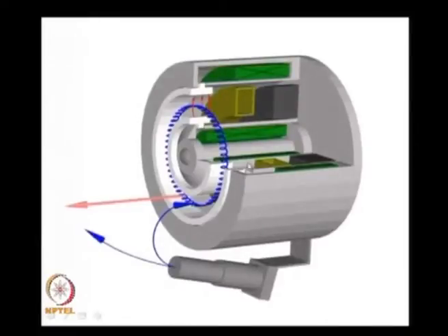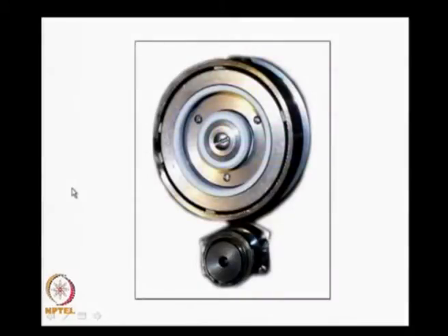Well, this is the picture of a Hall effect thruster. This is where the electrons are generated using a cathode. They enter the annular gap over here. There is a strong magnetic field in this particular gap, and therefore the electrons spiral. You have an anode here which pushes the charge out, and you get the thrust over here. This is the face view.